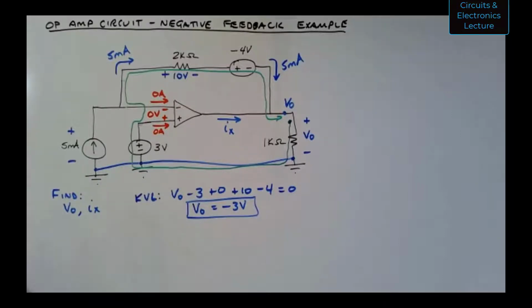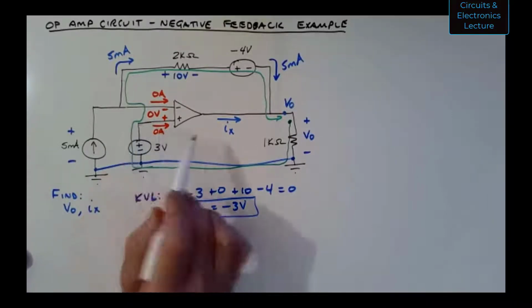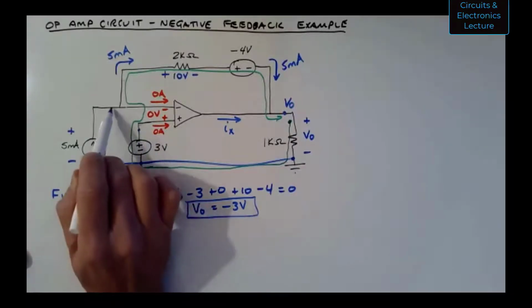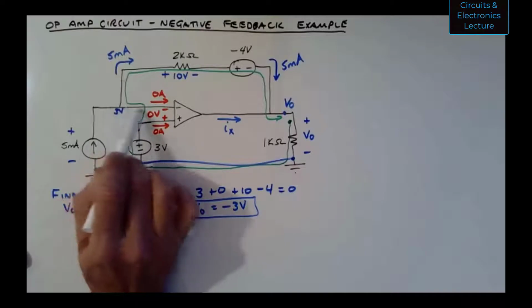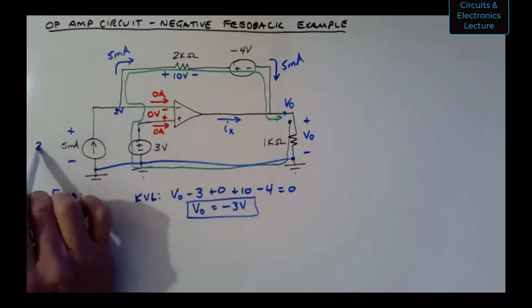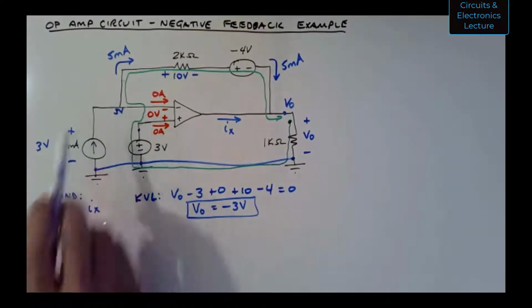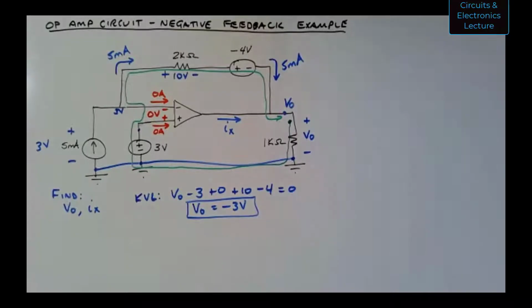Well, I know now that if I have 3 volts node voltage, let's say right here at the top of the source, then I have 3 volts node voltage at this node up here. So I know this is 3 volts. Like I could do a KCL equation. But before I started the analysis, I didn't know that was 3 volts. I can figure that out later. Okay.